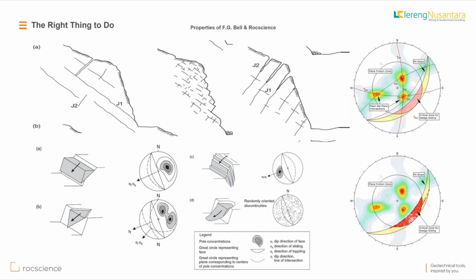You might use 2D analysis on plane slip surface analysis, or rock fall analysis, or even toppling. But wedge failure is a 3D problem, and you cannot account for this type of failure using 2D analysis. Yes, you might analyze it using kinematic analysis, but kinematic analysis still has its own limitations, such as the location of the wedge failure cannot be defined using kinematics.